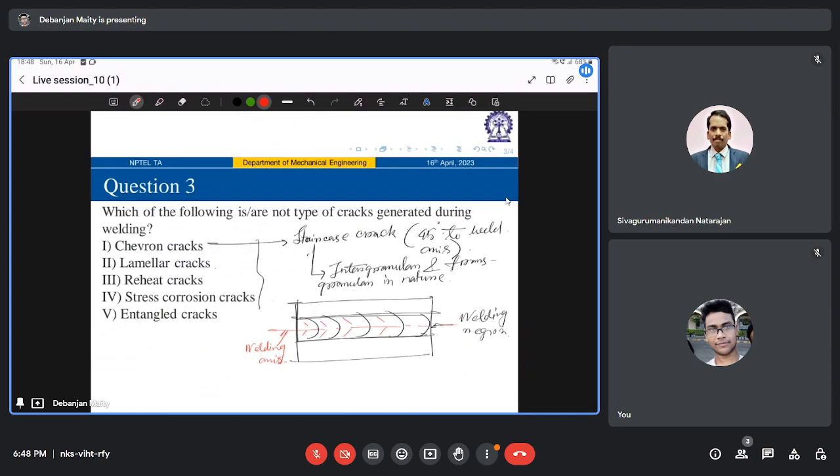And even though the nominal alloy composition lies in the single phase terminal solid solution region, right? So tensile stress induced by this volumetric shrinkage as liquid transforms to solid in the fusion zone, along with this non-uniform thermal contraction in the heat affected zone, can act on this constitutionally liquid film surrounding these second phase particles and in grain boundaries to produce these hot cracks, which we call liquefaction crack.